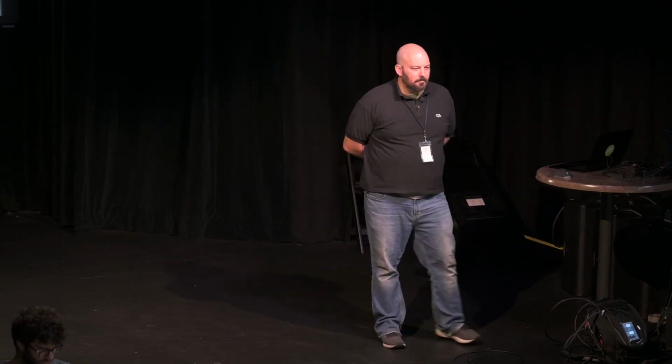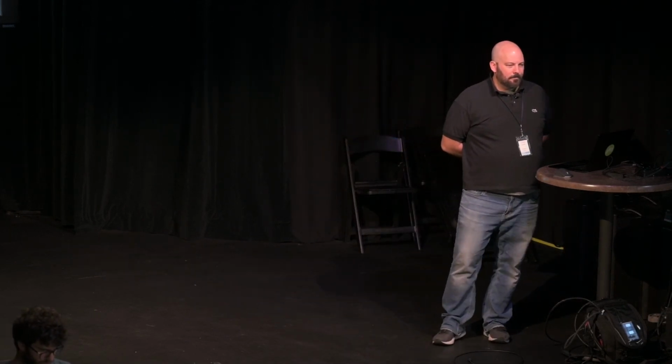Yeah, so to that point, it's actually graphs that are the worst for having that, because you're redrawing stuff when things are on top of each other. But then the other comment I was just going to say generally about updating UIs is to decrease how often you update it. Like your process might be every 50 milliseconds, but you definitely don't want to update your UI that often, especially if you've got that wiggle going on. So what rate do you guys use for UIs? 5 or 10? Five's good enough for most things.